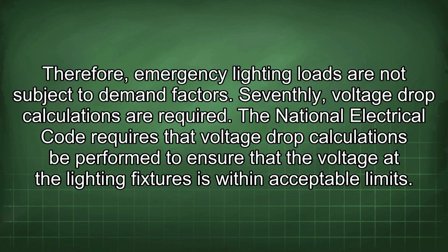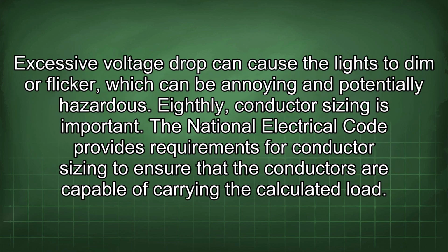The National Electrical Code requires that voltage drop calculations be performed to ensure that the voltage at the lighting fixtures is within acceptable limits. Excessive voltage drop can cause the lights to dim or flicker, which can be annoying and potentially hazardous. Eighthly, conductor sizing is important.